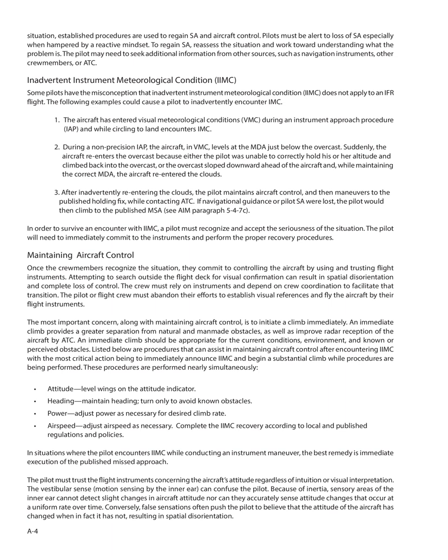An immediate climb provides a greater separation from natural and man-made obstacles, as well as improves radar reception of the aircraft by ATC. An immediate climb should be appropriate for the current conditions, environment, and known or perceived obstacles.